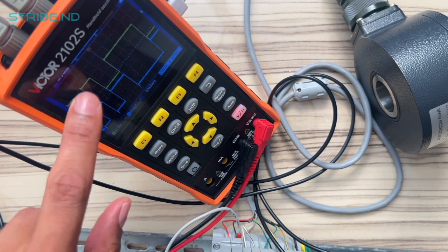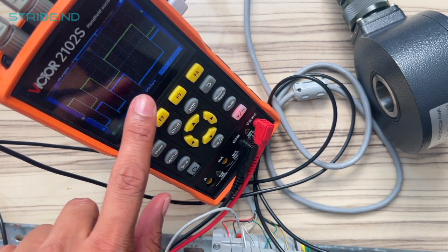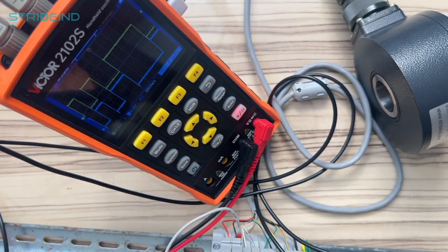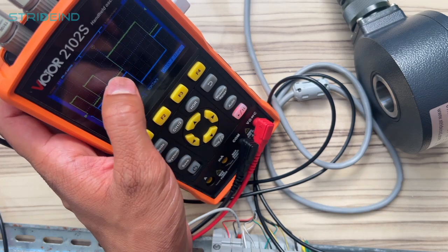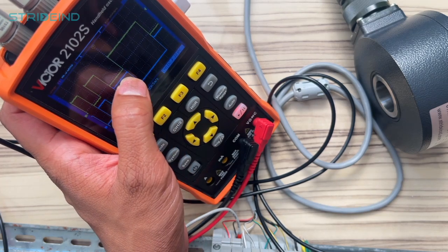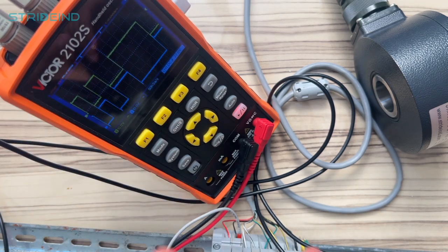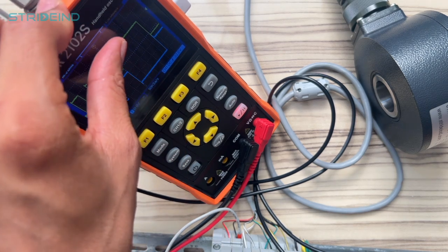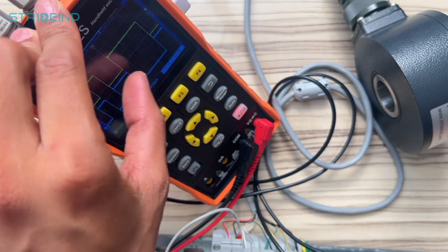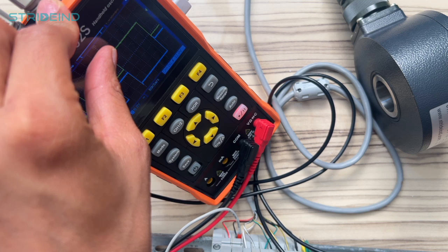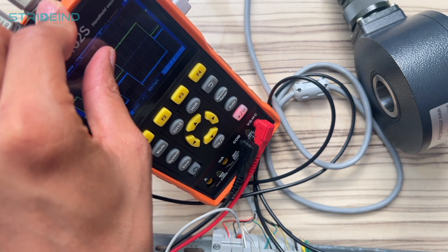This is your 0 volt, this is your positive volt, this is your 0 volt, this is your negative volt. Here one has positive volt, the other has negative volt, and here one has 0 volt and the other has 0. So what it is doing is switching this 24 volt from one channel to another channel. When channel A positive has it, A negative doesn't have it, and when channel A negative has it, A positive doesn't have it. So these are called inverted pulses. One has it and the other doesn't.